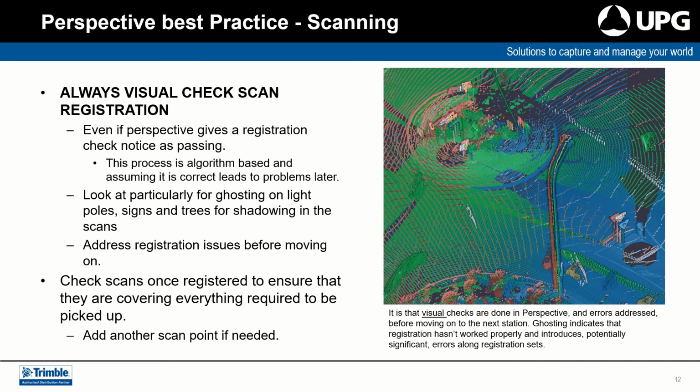Remember, for a long linear project, say 20, 30, 40 scans, if this is done at the start, while it seems small at this particular point, when it's collected and moved through the entire scan, that error can have large impacts later on.